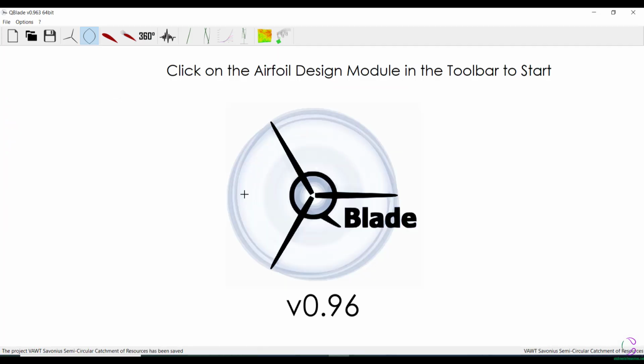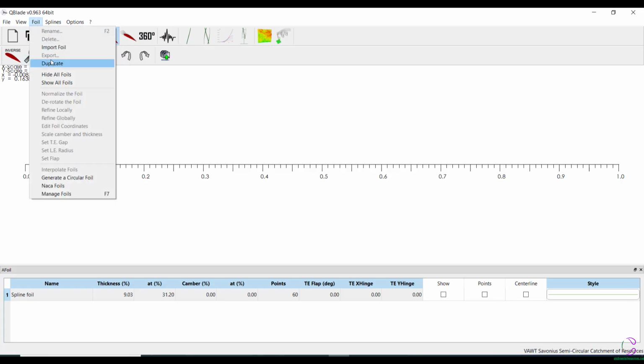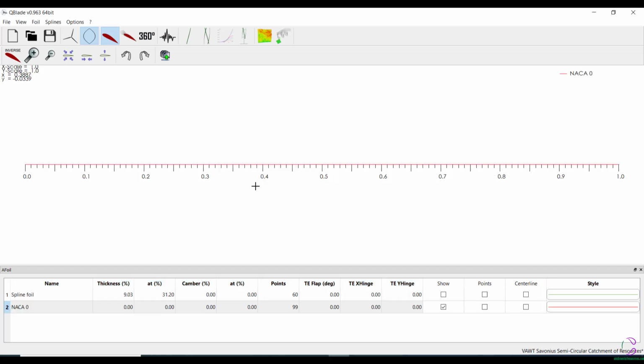So once you open QBlade, the intention is to generate an airfoil, and because there are already inbuilt airfoils, you can choose to select one. But in this case, for a profile that is quite different, assuming you are doing a lift-based turbine, you can then go and import your own points. You import points in order to generate your own user-defined airfoil.